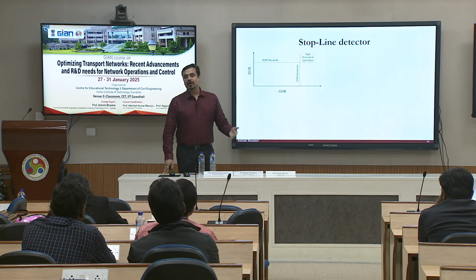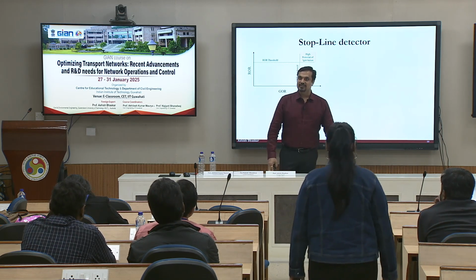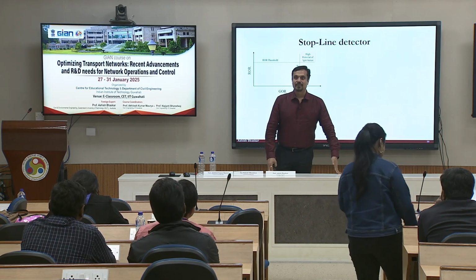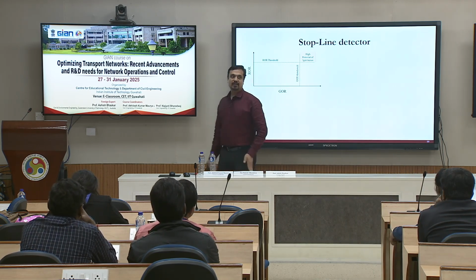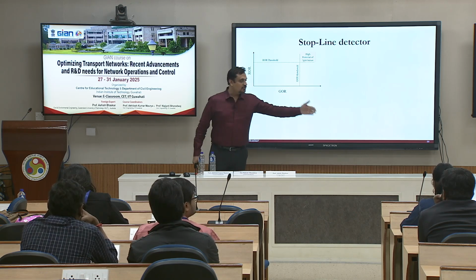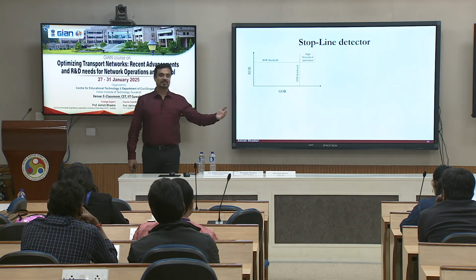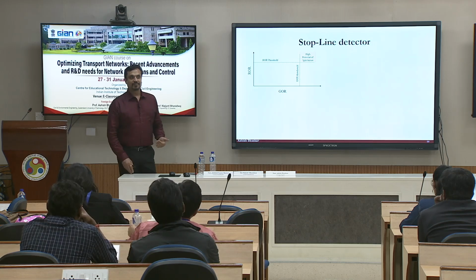So, this spillover from downstream means I have to make some improvements in my downstream intersection to avoid that spillover, right. So, my intersection I might have given a good split, enough green, but unfortunately the downstream is not able to serve properly. So, the problem is further downstream, fix that problem first, then only I can fix here.